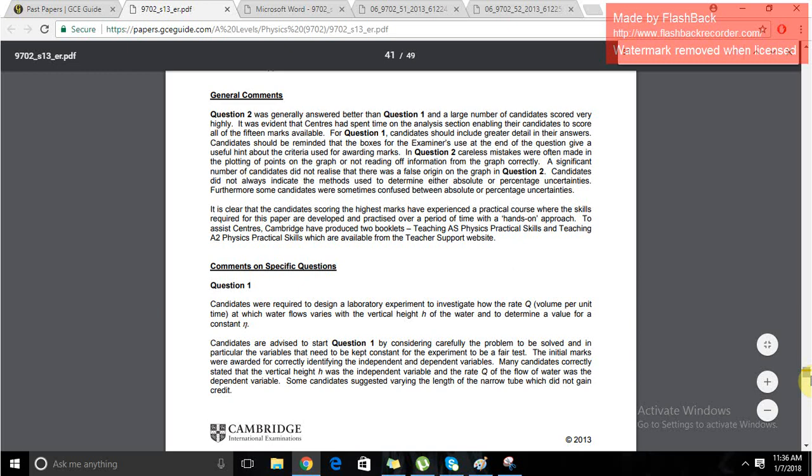One interesting thing was the density part, because whenever density is a part of the equation, even if it isn't the independent or the dependent variable, when you say density needs to be kept a constant, instead of that you must say that the temperature needs to be kept a constant in order for the density to not change. That is something we often miss out.